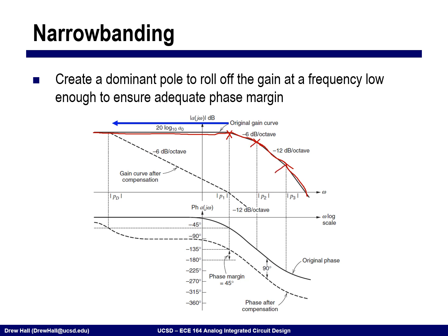We can also see from the phase response that if we hit these poles, and they're all very closely related, you would say that this particular circuit, if we were to find the unity gain frequency here, does not have much phase margin. Okay, in this particular case, it has very, very poor phase margin, in part because we're hitting these three poles all very closely spaced. Okay?